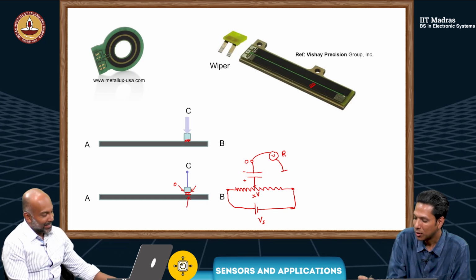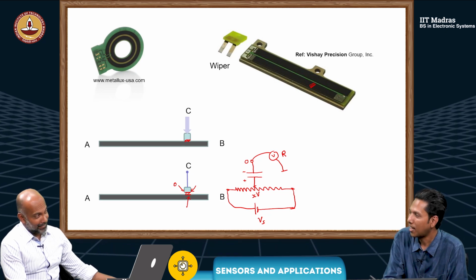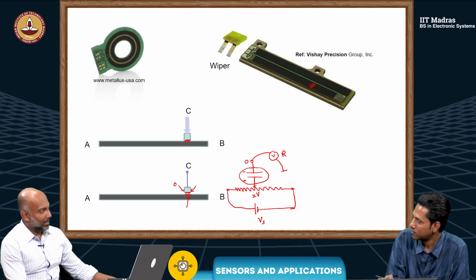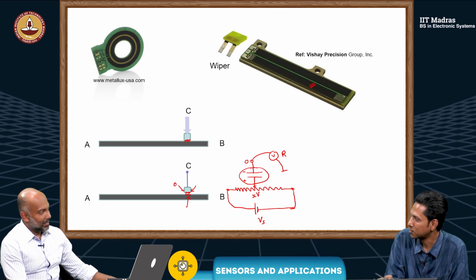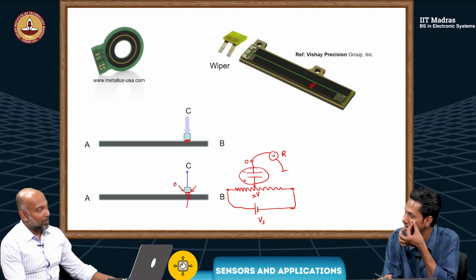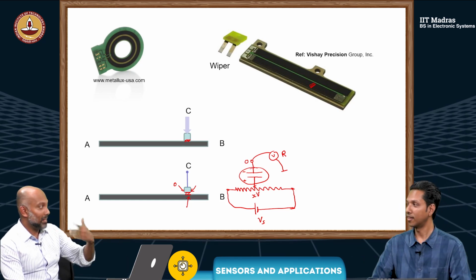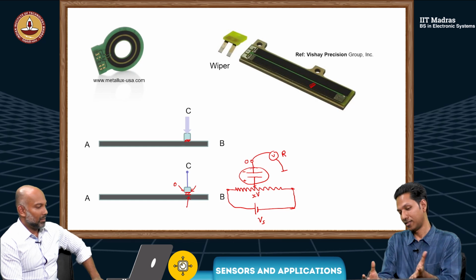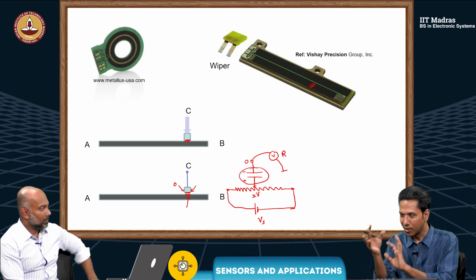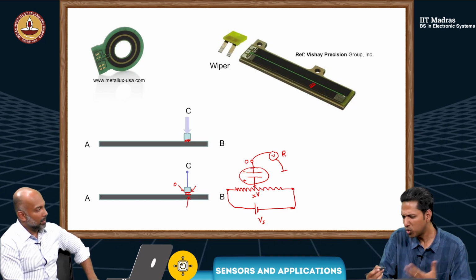So that means if I give a DC excitation like this, it may be hard to use this. Yes. Correct. We may have to use some AC excitation. I think in your back end now, your readout electronics is maybe a little more complex now. Compared to what, I cannot directly just put a voltmeter and measure. So what you're saying is if you can do something there, yes, probably we can still measure. Maybe. If I do that, will there be some benefit?